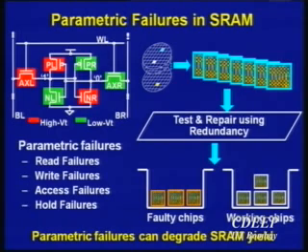So, a 6 transistor cell, and I guess most of you are familiar with it, a 6T SRAM. How do I read from that SRAM? Don't worry about the red and the green that I'm showing there. But for the time being, how do I read from the cell? Let's say that I have a 0 on the right side, so I pre-charge with bit lines high, right? Once I pre-charge with bit lines high and I turn on those access transistors AXL and AXR, what's going to happen to logic 0? That's going to go up a little bit, right?